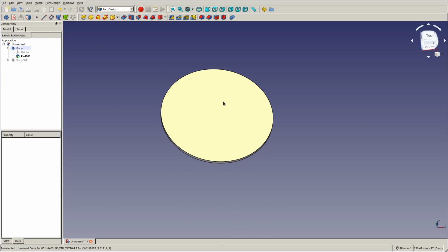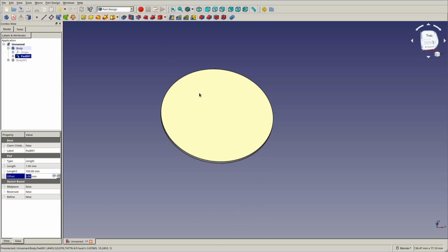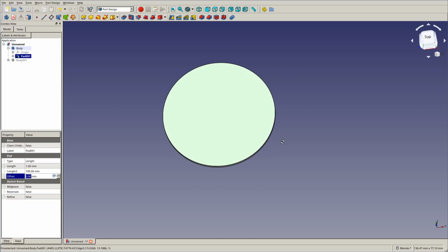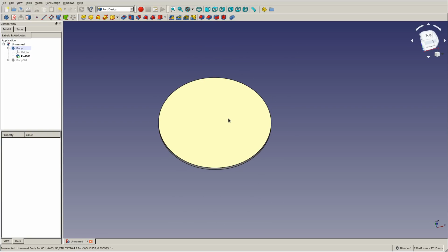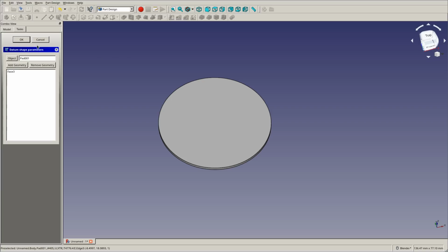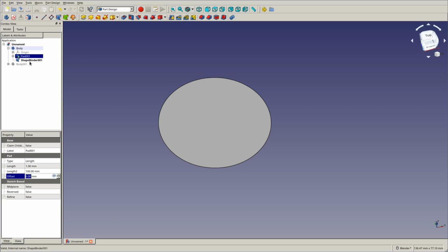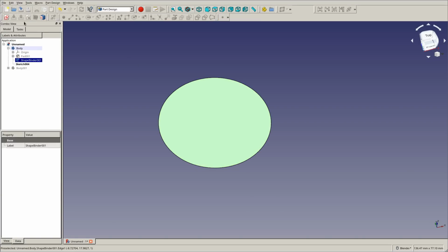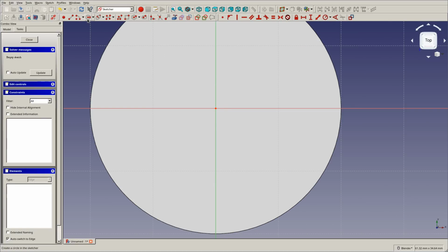And now I want to make the space for the actual electronics and magnets of the motor that go inside. I'm not going to design those. I don't need to go that far. So again, I need to map a sketch to this face, and I could do it directly, but I prefer making a shapebinder object and mapping a sketch to it instead.